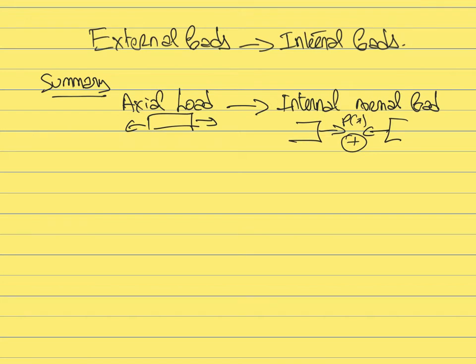And for consistency, the sign convention that we decide is that a positive internal load is a load that is going to cause an elongation rather than a shrinkage. So that's a load that is always pointing towards the outside. So that's the first case. That was the case of the axial load. Then we saw the case of torsion.